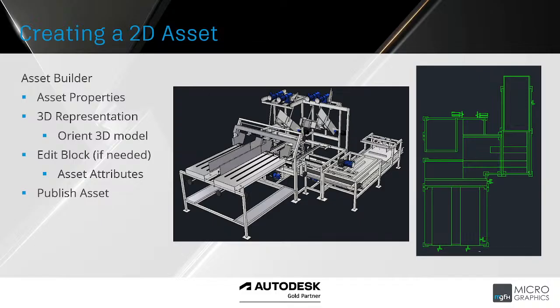Once you have your block, you would then go into the asset builder. And part of the asset builder would be to set up your asset properties that we just spoke about on the previous page. So you would fill in your descriptions, your part numbers, all the information that's required to identify the asset itself. And part of the asset creation in AutoCAD, or from the AutoCAD side, is to link a 3D representation.